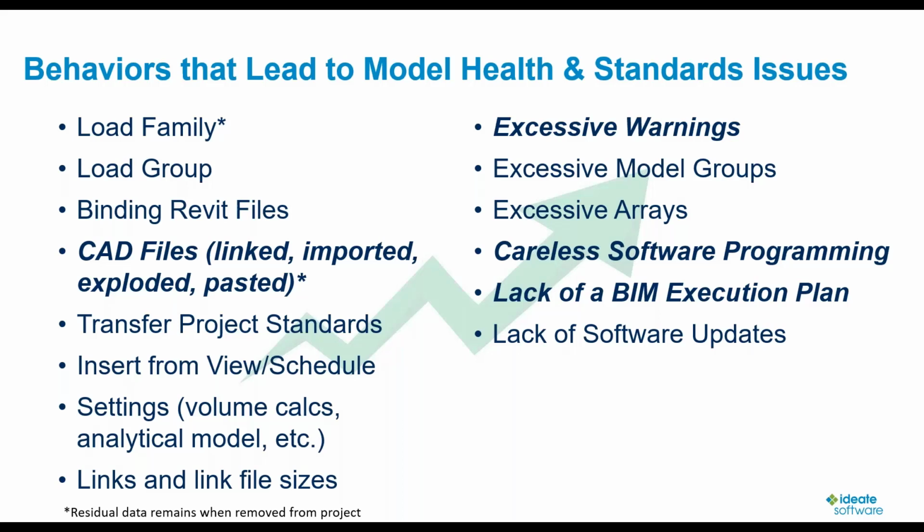Loading groups, binding Revit files. Again, if you're linking Revit files and binding them, you're getting all that stuff from that Revit file into your current Revit project. So same thing as with loading families, best to vet that stuff before you load it up.